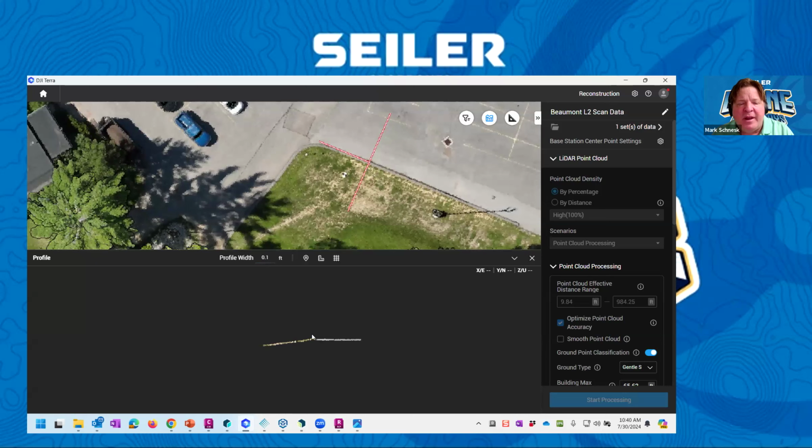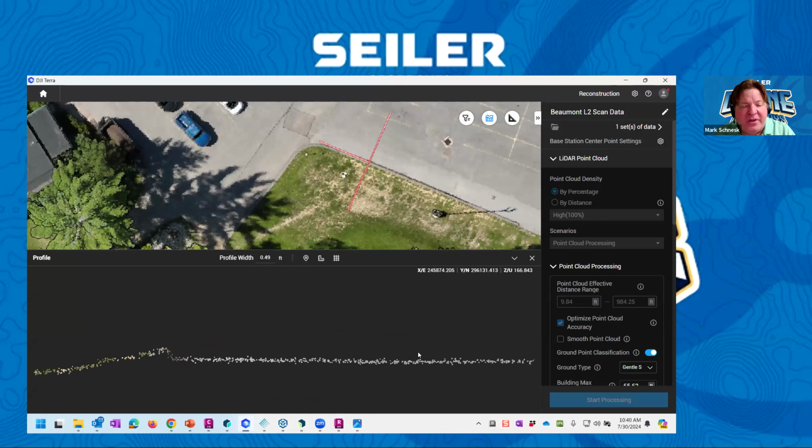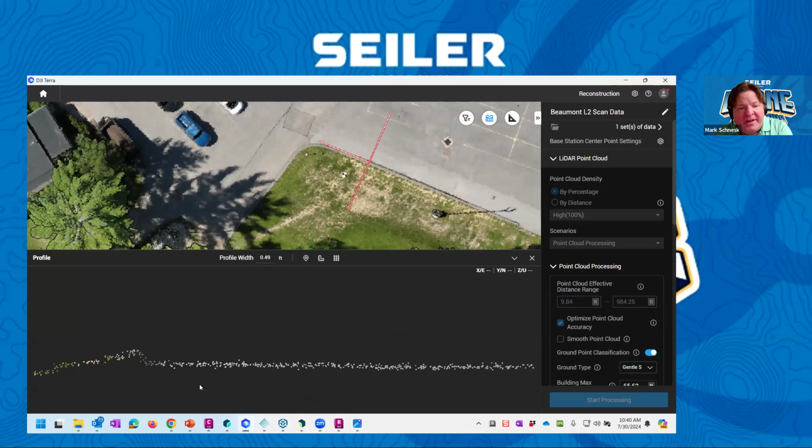So in the plan view here, I can zoom in and see my point cloud. And what you're seeing is basically that stretch. Maybe I'll make it a little bit bigger here. Maybe we'll go 0.5. There we go. Little thicker section, a little meatier there, kind of gives us a better feel of what's going on. But there you can see that noise band. There's my top of pavement coming in this way. There's my curb, and then there's my slope going off the back.